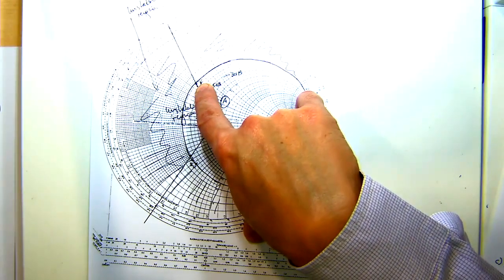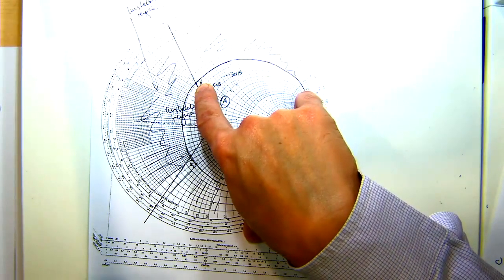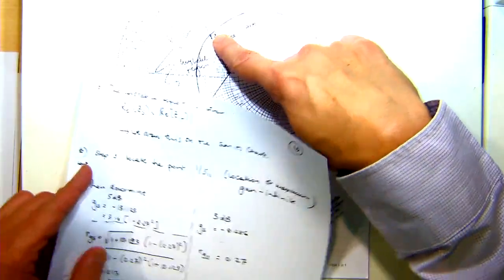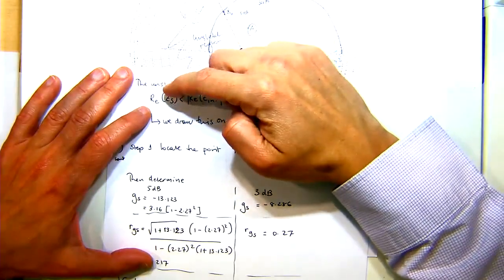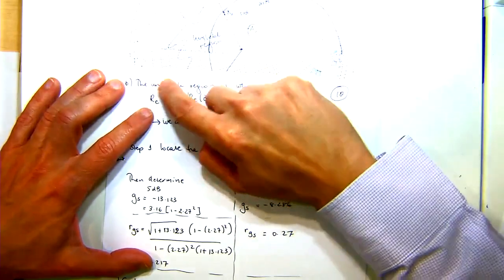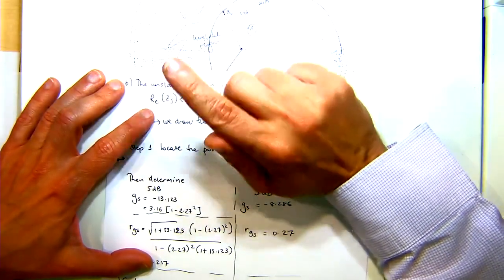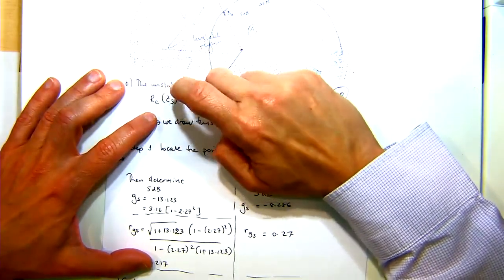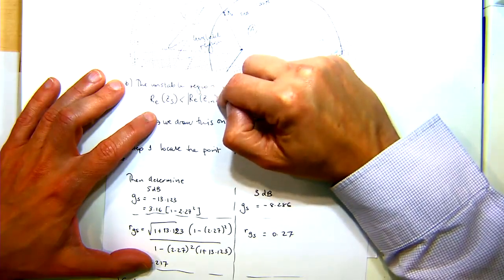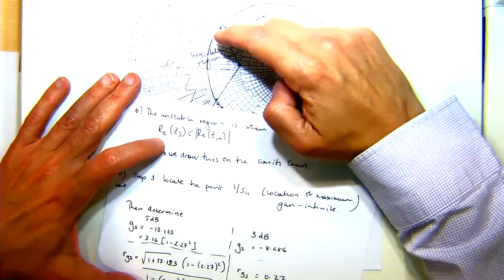And what we've said is, in order for it to be stable, we needed to look at the regions where, here I'm saying the unstable region, but the region where it's stable, we want the real part of ZS to be greater than the real part of the input impedance. And that's why I've drawn this circle.